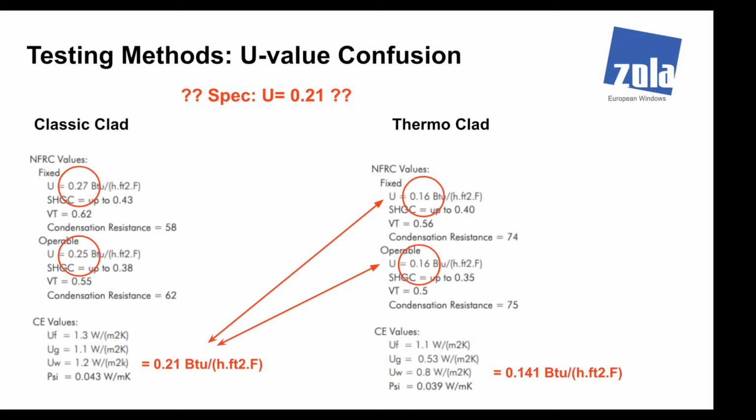Another thing about NFRC I want to throw out is that NFRC likes every glass and every frame combo to get tested. So if you deal with somebody like Marvin, they have about 15,000 NFRC tested windows because of every little combo they do. They just keep testing. They have in-house, they just test it. We're not going to go do every glass and every frame.